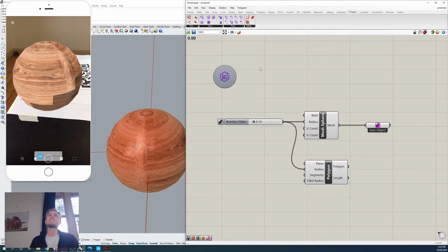It's just a little pendant that sits here, but you'll notice straight away when we drop it onto the canvas that there's a change in this number slider. There's a little Fologram logo that's appeared right next to the number slider, and this gives us the ability to send the parameter to our device so that we can control it remotely, and we don't need to go into Grasshopper and move the slider around anymore. To turn it on, I just need to click on that logo, and you'll see straight away it turns purple, which gives you an indication of which sliders are connected. If I click on this sync parameters component, you also get a little trail that shows you which parameters are actually being synchronized right now. You'll notice that nothing's actually changed on my device right now though.